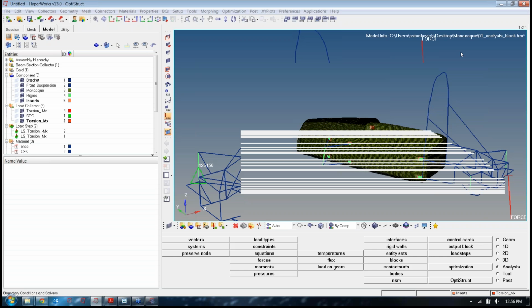Yeah, so if you have multiple stacks, then you'll have different outputs for those. You'll have to run an optimization on each stack, essentially, and you'll get different results for each laminate that you're optimizing in that shuffle phase.